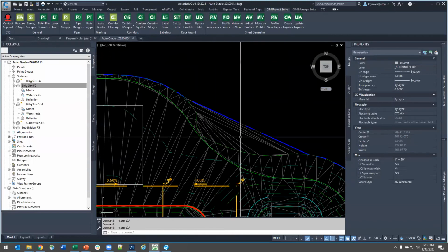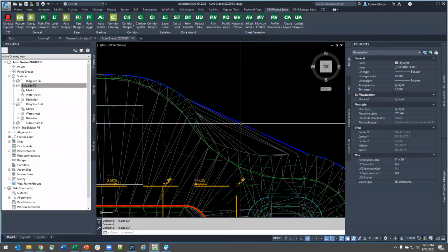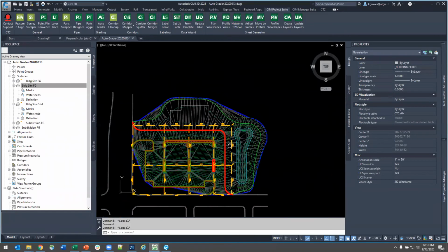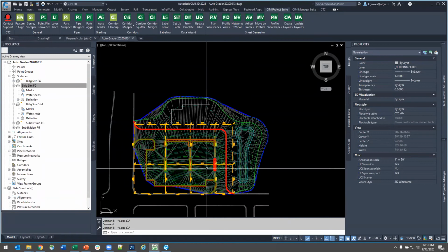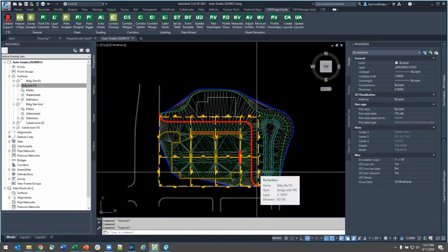Just note that you're always going to see those whenever you're doing this with AutoGrader or with manual stepped offsets and the rest of that jazz. You will need to come in with your boundaries and just chop off those interior curves with your feature lines or with your outside boundary. So with that, that concludes what I wanted to talk about with my site grading workflows.